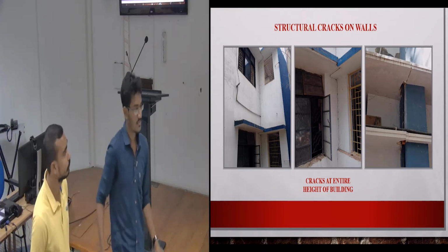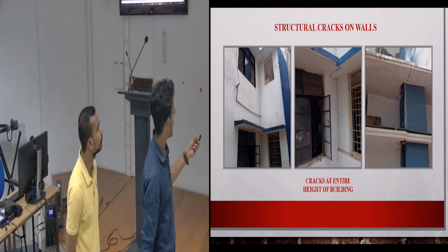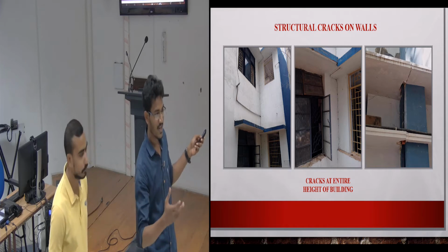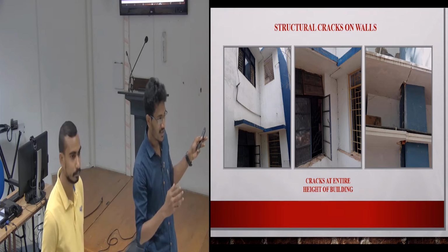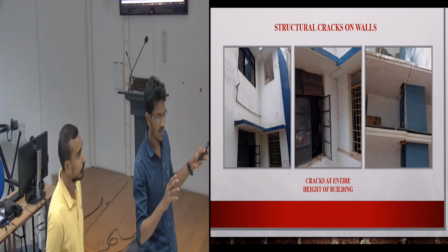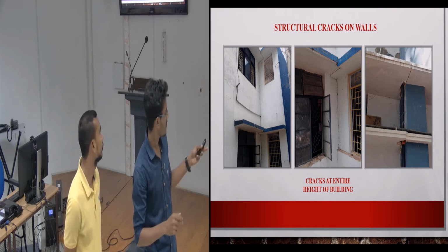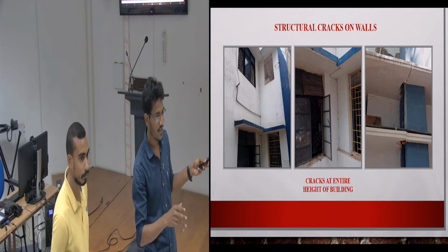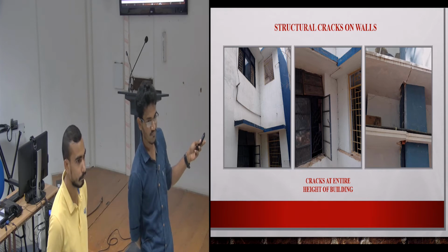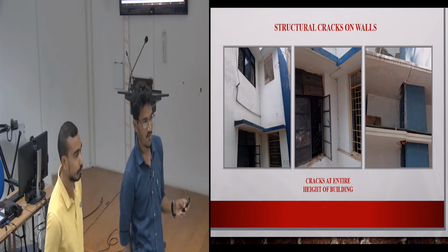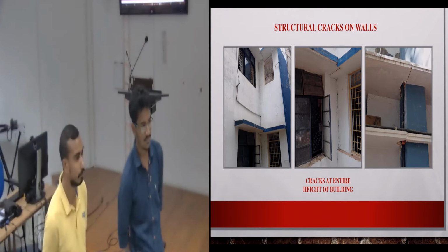Can you give an explanation why there is vertical separation? Maybe due to thermal expansion, because due to temperature variation, the structure will contract and expand at a particular period. So we should provide thermal expansion joints every 100 feet. Maybe a lack of thermal joints. And also the foundation. We are not sure about the foundation of the old building, whether it is in the same line.